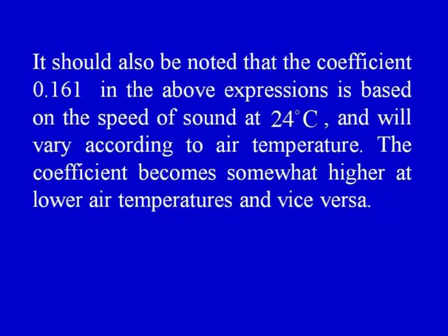It should also be noted that the coefficient 0.161 appearing in the above expressions is based on the speed of sound at 24 degrees centigrade and naturally will vary according to air temperature. The coefficient becomes somewhat higher at lower air temperatures and vice versa.